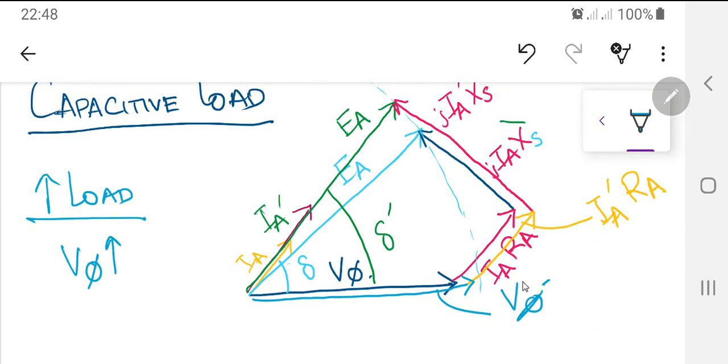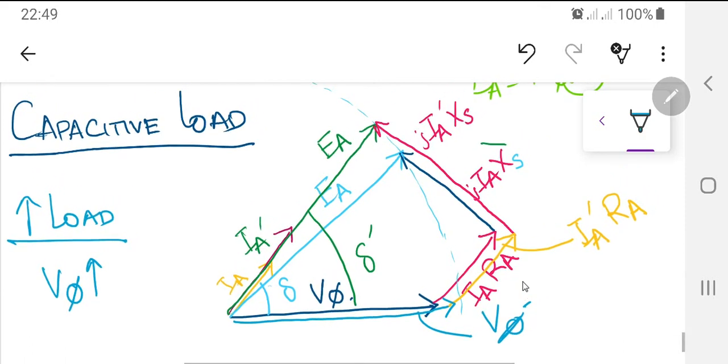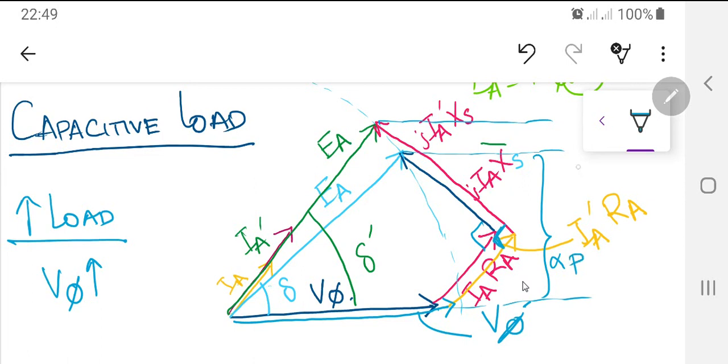This is very, very important in the exam as well, that you draw it with different colors, because otherwise the teacher cannot understand which one was drawn first and which one was not drawn, and it's very difficult to actually understand. So kindly, whenever drawing these phasor diagrams in assignments or in exams, please draw it with 2 or 3 different colors, just like over here, so you can actually show what has happened. This angle has to be 90, this angle has to be 90, at least when you are drawing it with a free sketch, because they are not according to some scale. This is very, very important over here. So again, you can see over here, if I draw the perpendiculars over here, this one is proportional to P, and over here this one is proportional to P bar.